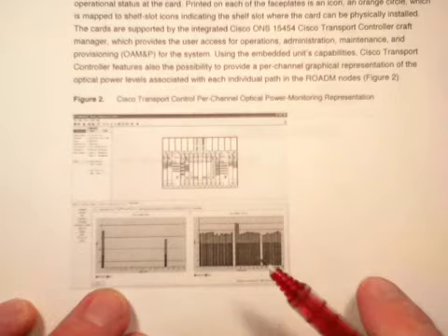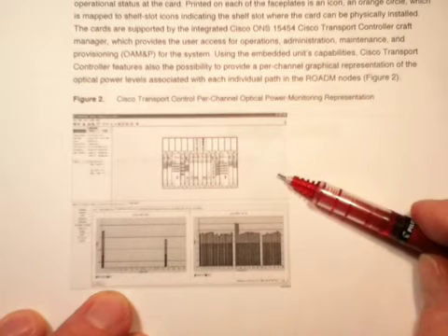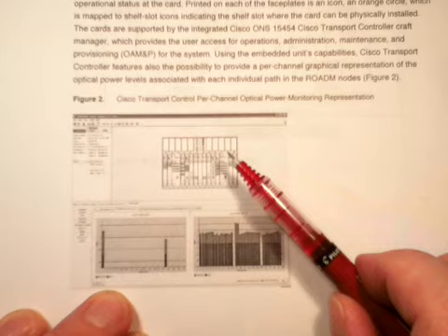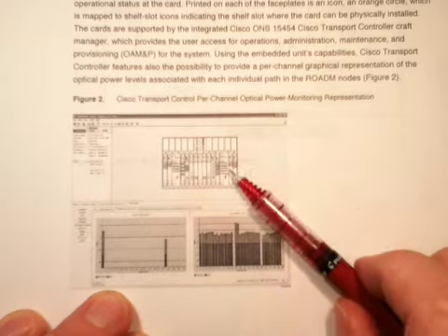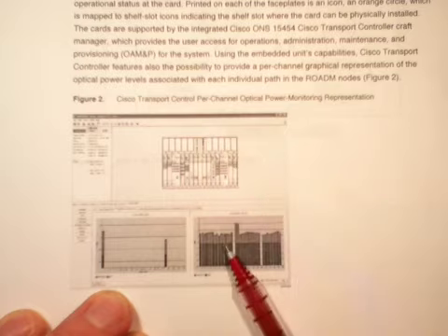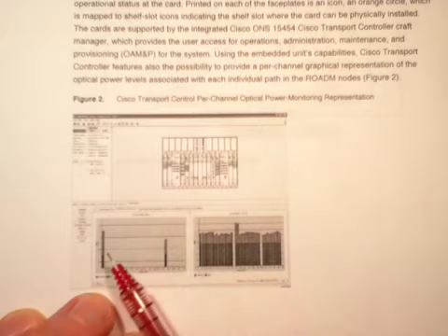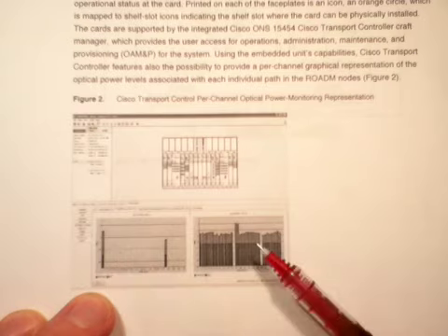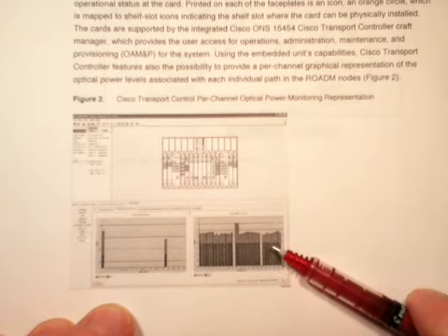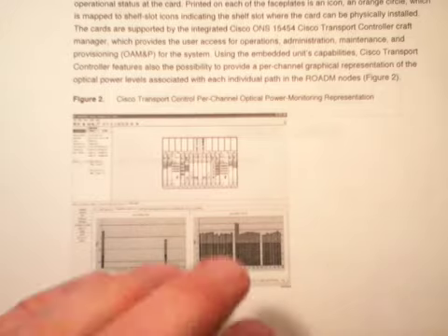First of all, this picture is really small and it doesn't help to blow it up, unfortunately. This is a picture of the Cisco software, which is used for provisioning these systems. And on this you can see a graphical representation of the 15454 platform with the various cards in it. I believe the card that is highlighted here is the one where we have data showing below here. And in fact, I believe that what they're showing, although I can't read it, is a couple of add wavelengths, and then this is the wavelengths that are being passed through the system as express channels. That is neither adding nor dropping. That's called an express wavelength. And so basically you can use software to provision and control all of the things that are going on these cards.